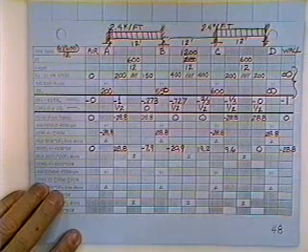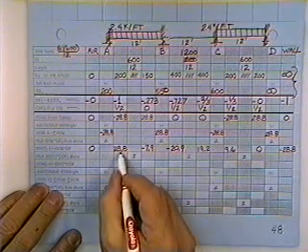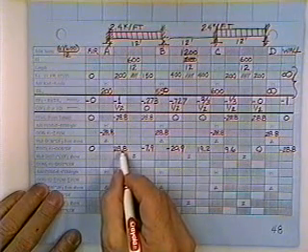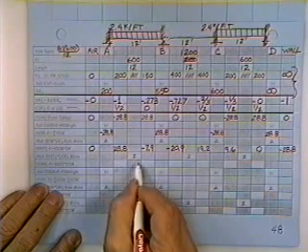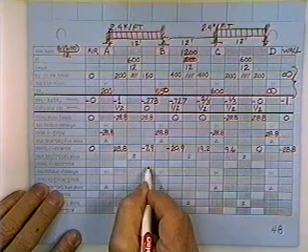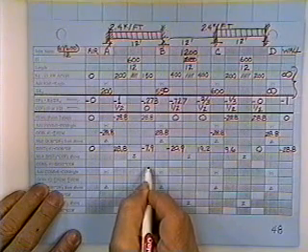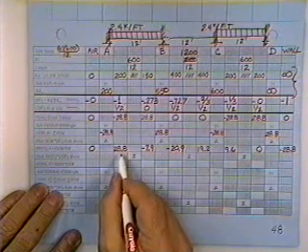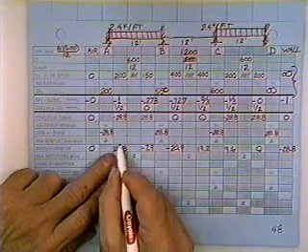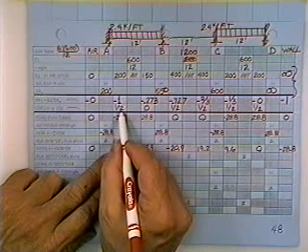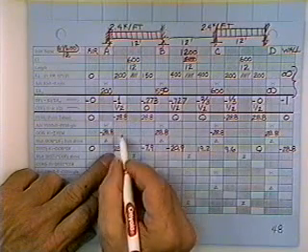Now, when this 28.8 came into this member, some of it probably went across to the right. Because normally when a guy cranks on one end of the member, some of it travels across the member to the other side. You can find out how much of that happened by looking at the carryover factor directly above the 28.8.